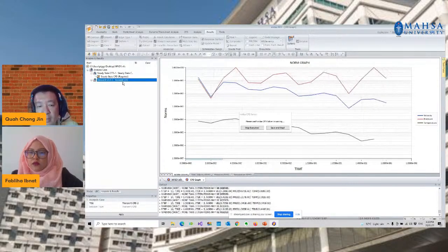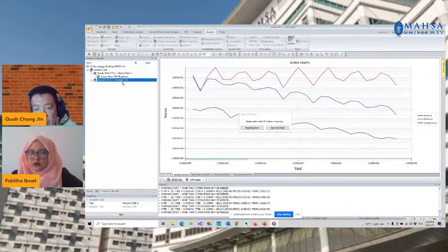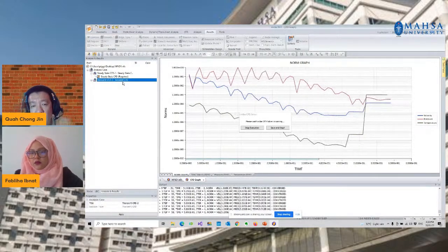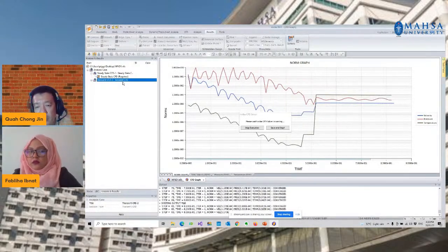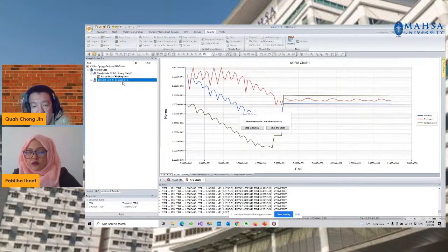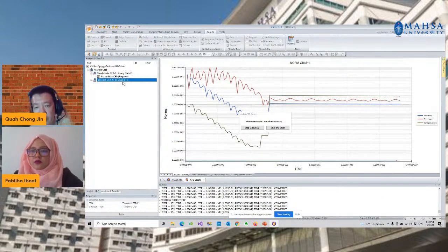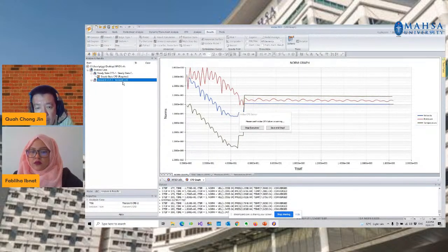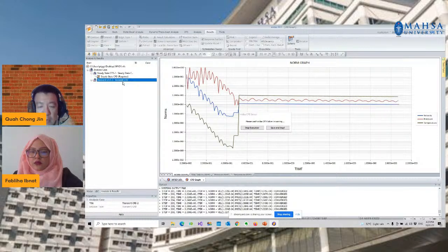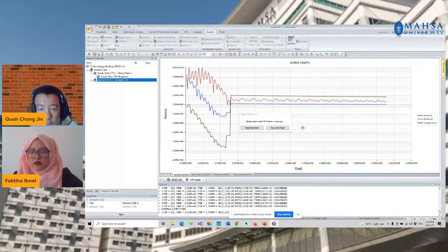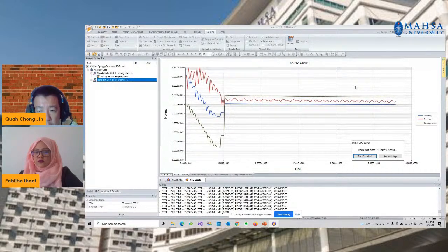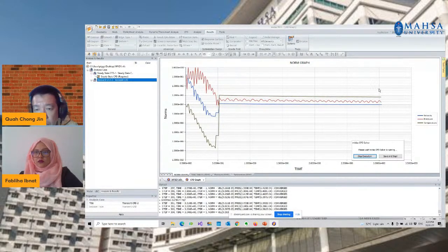Okay, so this is transient, which means that the time step is very important. What you are seeing, the time step, is actually the physical time step, how the flow goes starting from 0 seconds up to the final time, and also how the heat transfer starts from the inlet temperature, distributing all over the region of the elbow pipe up to the outlet as well. Right, so the same idea. We're monitoring how the norms, or the residuals, or truncation error behave. It looks very steady at the end of the simulation.